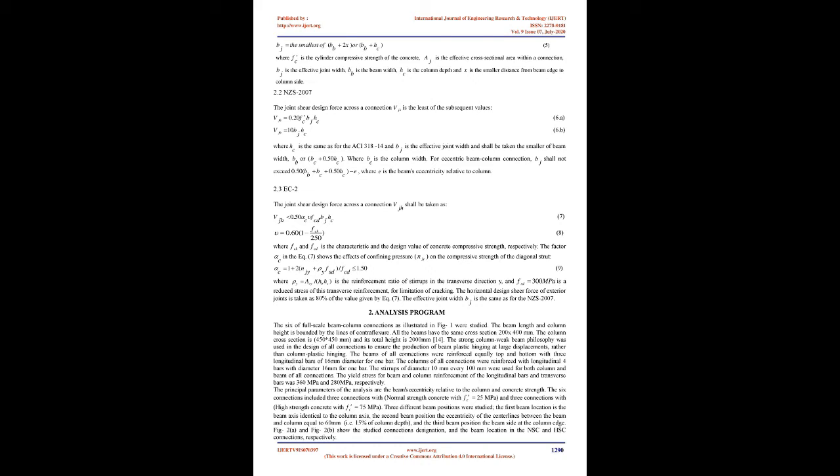1. Introduction. In most cases of construction of beam column connections, it is often required to construct an eccentric beam relative to the column. This eccentricity between the beam and column contributes to the creation of torsion in the contact region parallel to the exterior edge of the structure under lateral loading. This torsion in the joint creates extra shear stress and can adversely affect the joint's inelastic behavior.